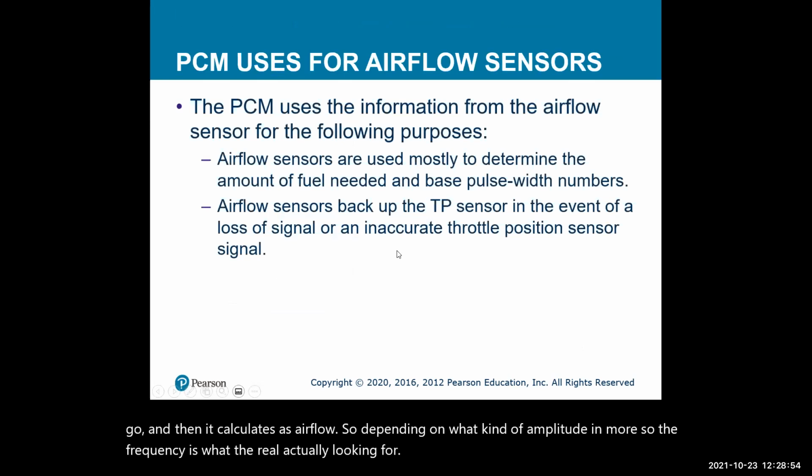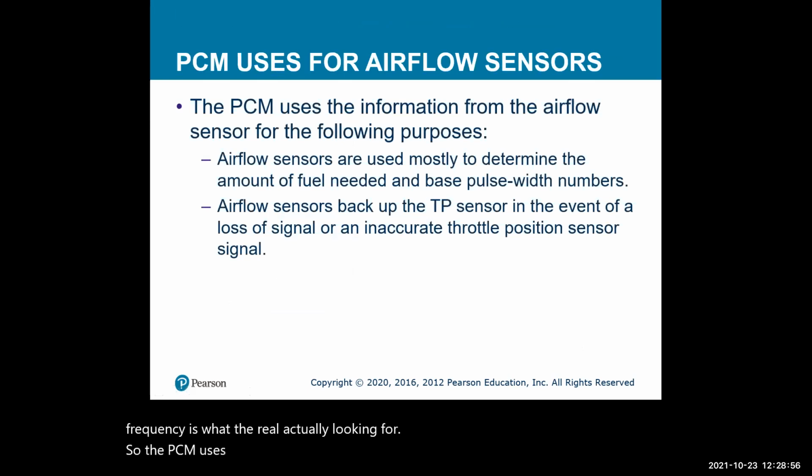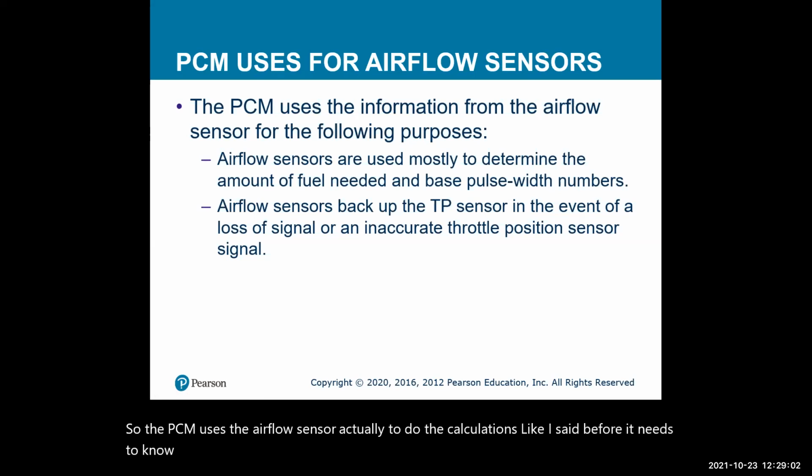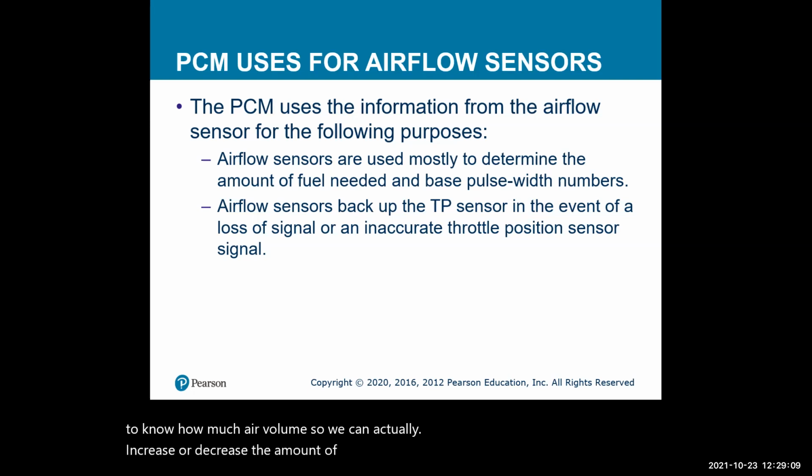The PCM uses the airflow sensor to do the calculations. Like I said before, it needs to know how much air volume there is so it can increase or decrease the amount of fuel that it needs. It's going to open up these injectors.